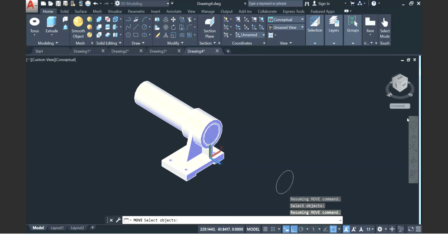If the assignment asks you to construct a 2D object, geometrical drawing, then you need to put a dimension. For this particular 3D object, you need to convert it to become an orthographic projection, with a top view, front view, side view, and then you put the dimension on that, not on the 3D object. Oh, okay.